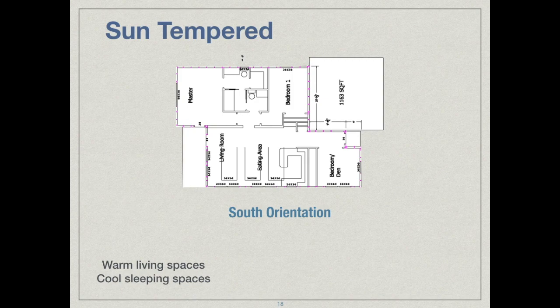So a southern orientation is always a really great idea in order to save energy, but also to save money. Now, it doesn't mean it's an essential element of all zero energy homes, because not every site has the capacity to do this. But if you do have good sun, or even marginal sun, it might be a good way to save some energy without really spending any money. All you have to do is put some thought into it.